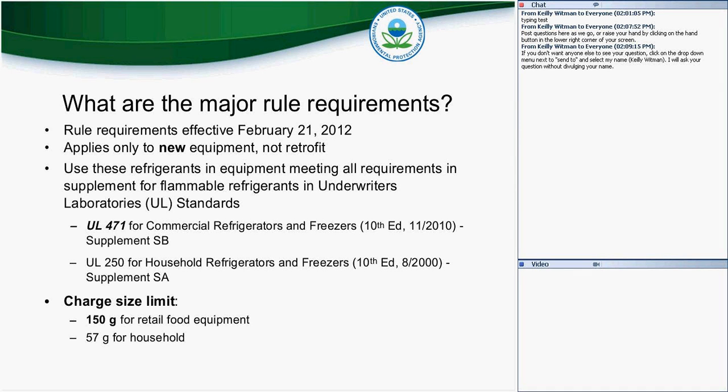There could be further discussion on that, but for most of you, it's probably good enough to know that's the size of equipment we're talking about. Usually with hydrocarbon refrigerant, you need a charge size about half of what you need with a halocarbon refrigerant, maybe 40 to 50%.